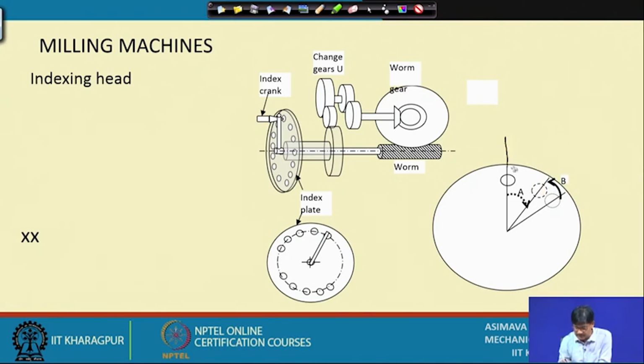So, let me draw it, this one only. This is the virtual hole, it is not there, but this rotation would have been 1/71. This is what I want to achieve. If the crank can be moved from here to here, my job is done. But what happens when the crank comes this way and reaches this position? It does not find a hole, the hole is far off. If it travels further down, then it will actually be traveling 1/70 and our job is not fulfilled.